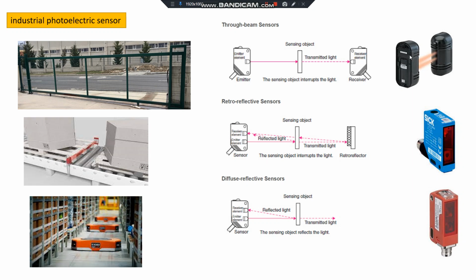We locate the receiver here and the emitter just opposite, and when we connect the cable there should be a connection. When a car or any human comes between them, the sensor will detect the person or car and will stop the opening or closing of the door. In this way, we make the doors secure.